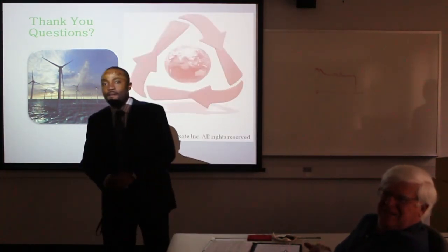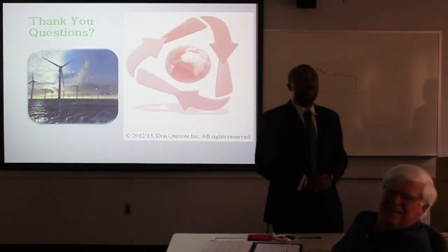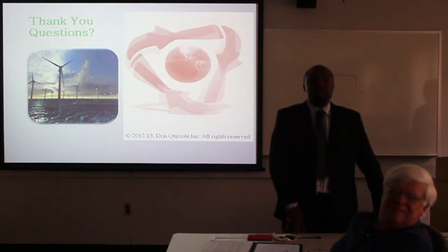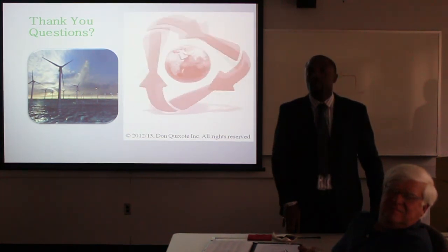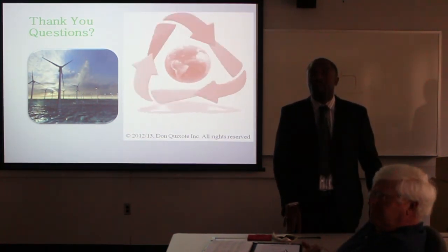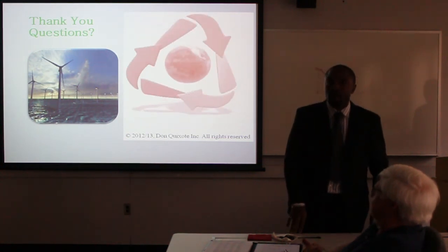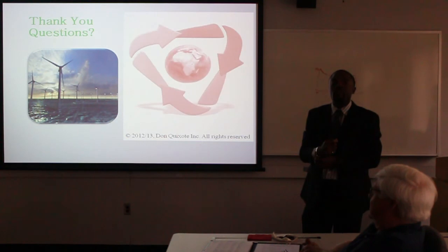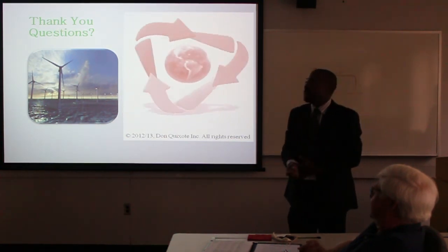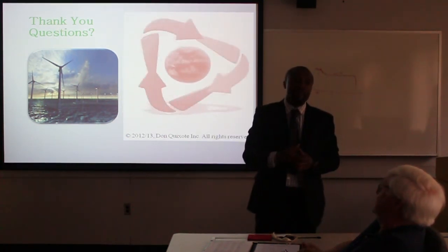Dr. Wong: So is it actually the gyroscope that's controlling the tilt angle? Yes. So how much force does it generate? How much can it control? For example, if there is a 10 miles per hour gust of wind, can you control that? Yes. Our design was for 25 miles per hour.